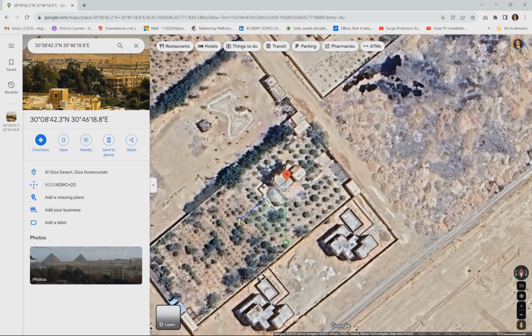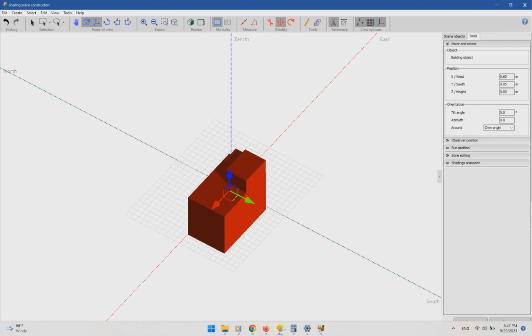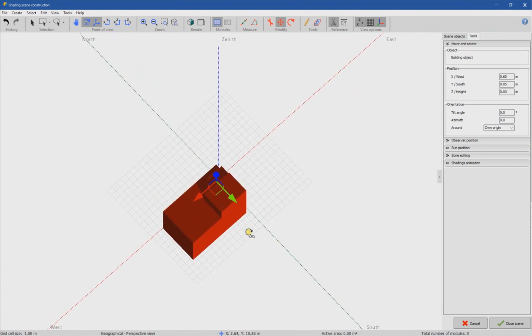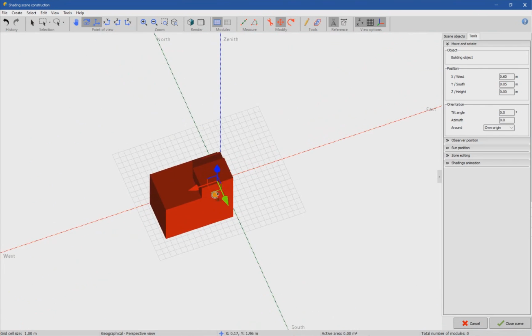If I would like to make sure, if you move this one, you will see angle 0 until here, approximately 50 degrees, okay, perpendicular to it. So we have 50 degrees with respect to south. So that is what I'm going to do. I'm going to the program like this, and I'm going to adjust this to form 50 degrees with south.